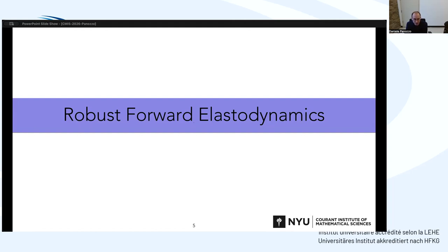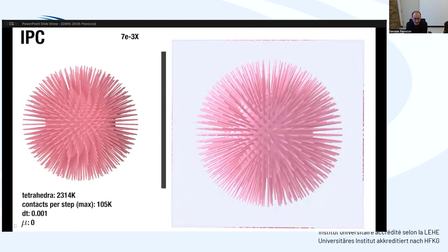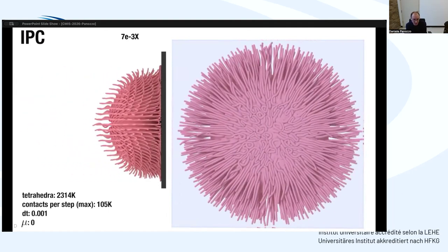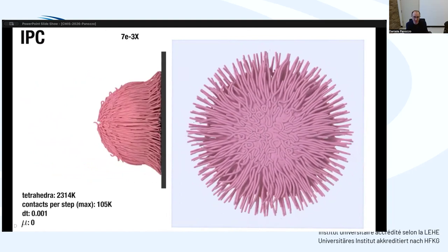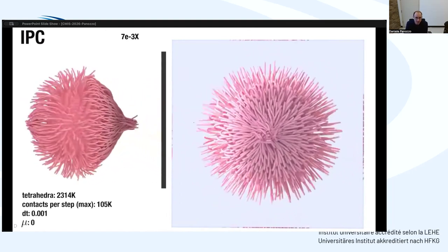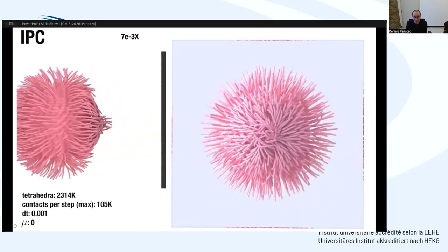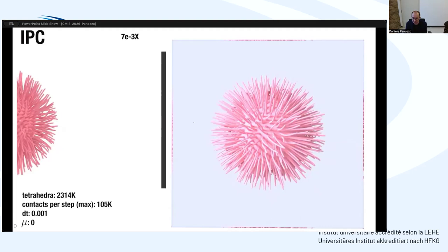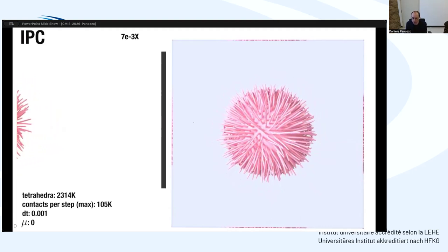So what I'm trying to do is to solve very large-scale deformations where contact surfaces are not specified a priori. They are just derived from geometry. This is 2.5 million elements, around 100,000 contacts per step. And in here, there is a guarantee that every frame in this simulation is going to be intersection-free. Of course, I'm playing things in real time here. These are absolutely not real time. This takes like hours to days to run each one of these sequences.